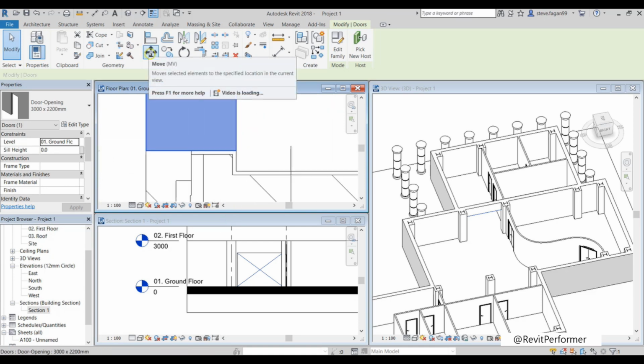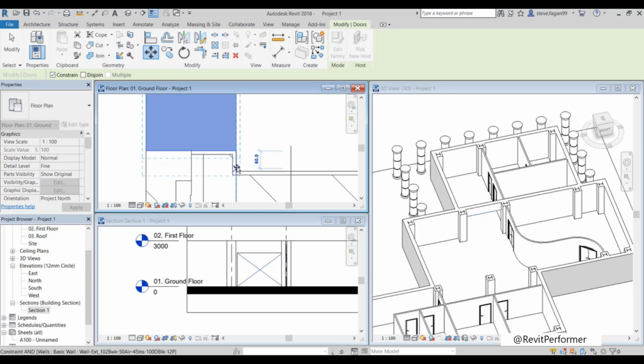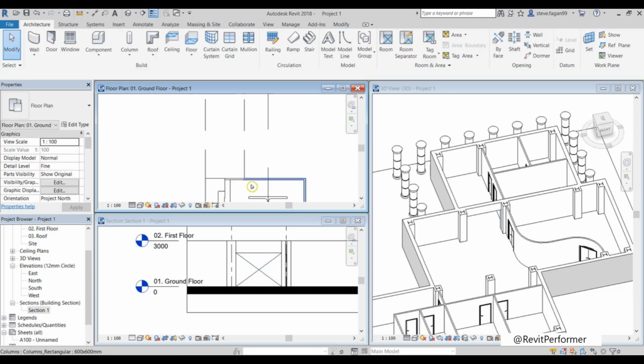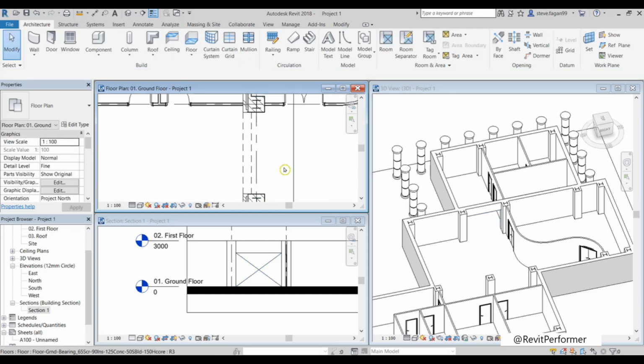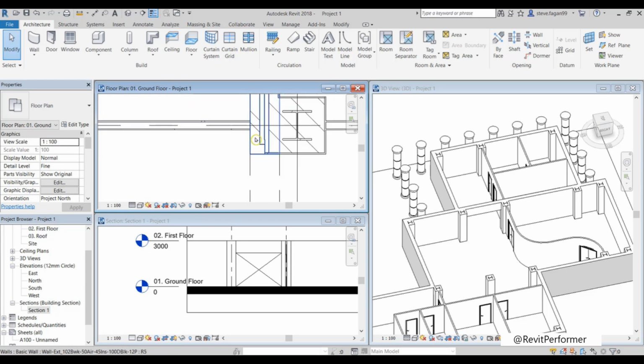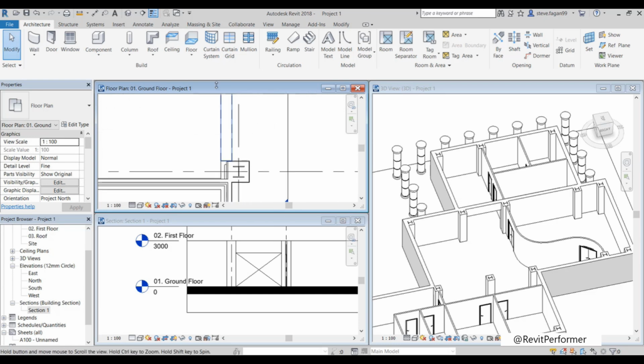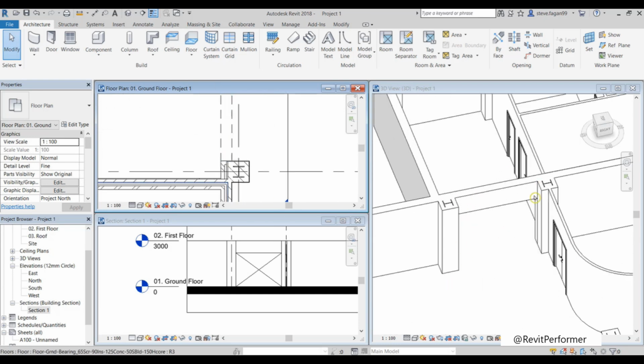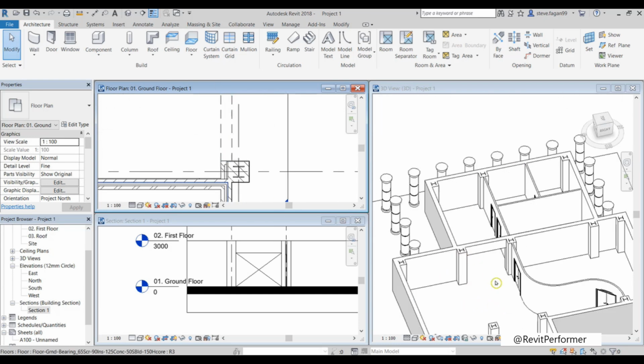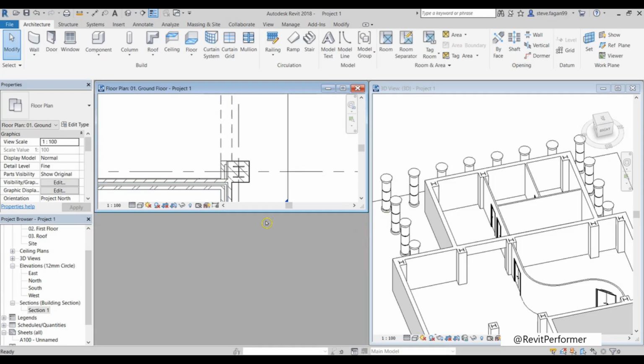So I'll use my move tool because that's an accurate move. Select my start point and finish. So in there, that is now my structural opening. And as you can see, the brickwork returns back into the blockwork and the plasterboard again also overlaps. Now in my 3D view, we have the nice opening now between the two sections of the buildings. And we can now close down the section view.